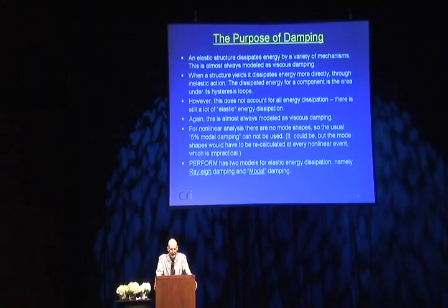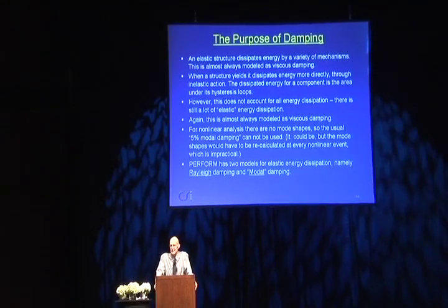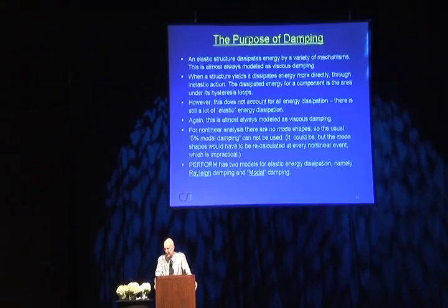So if it's an undamped structure, it is going to vibrate, but if it's damped, we know from experience that energy will be lost. It'll be dissipated in some way, and it'll be dissipated by a variety of mechanisms. It could be somewhat inelastic behavior. It could be rubbing of partitions. It can radiate energy into the soil.